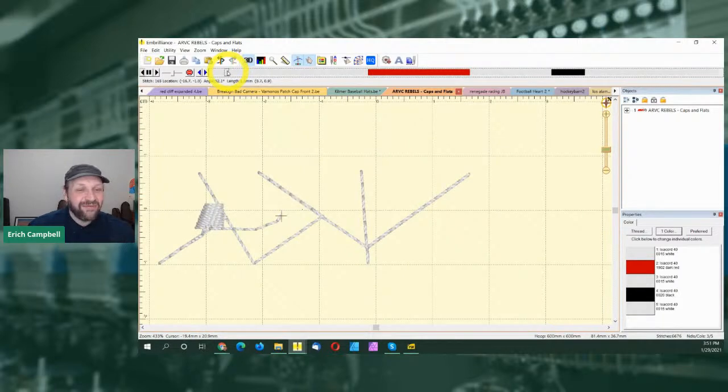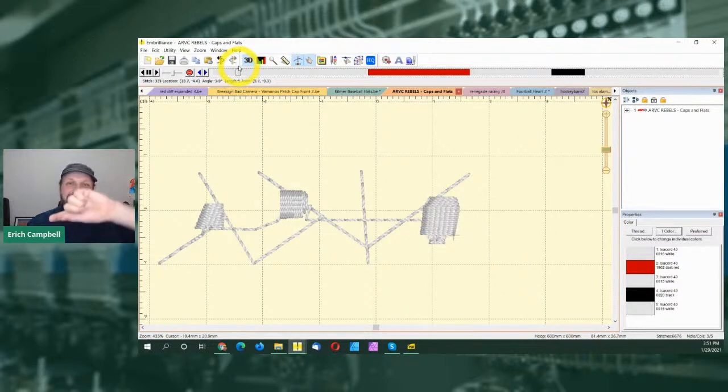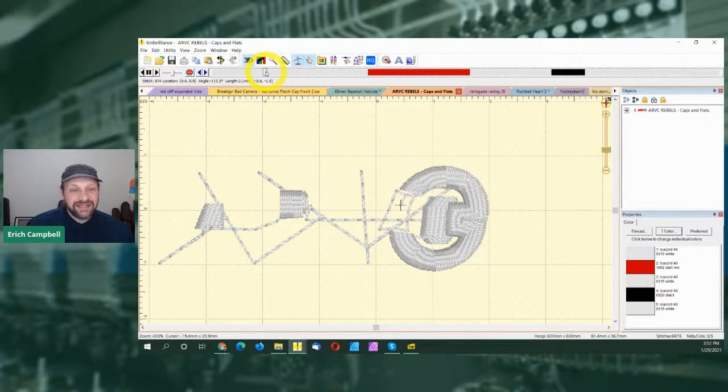Then you're going to see that I've run some of the interior slugs first, because I wanted those in place before I started working on the border. And then I worked back out. In the center of the C, instead of letting the border track all the way around and having a hole that doesn't support, we wanted to fill the area. In this particular piece, I wanted it to be satin stitch. I didn't want a big fill under the whole thing. We wanted more texture and to have the border look like a border all the way inside. So I went in with satin stitch, and then I ran this border on top, and that border does have a split in it, so it shows that texture.